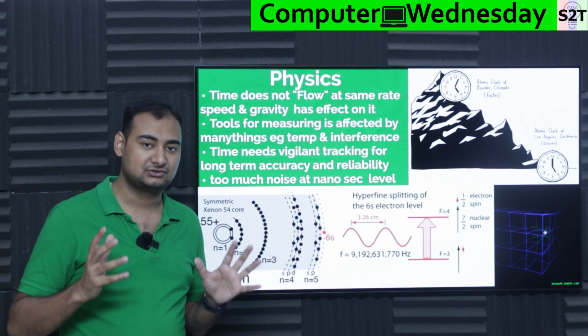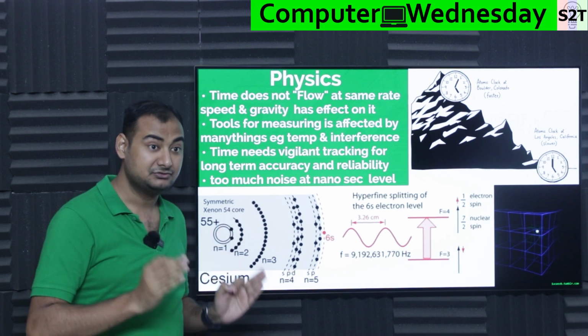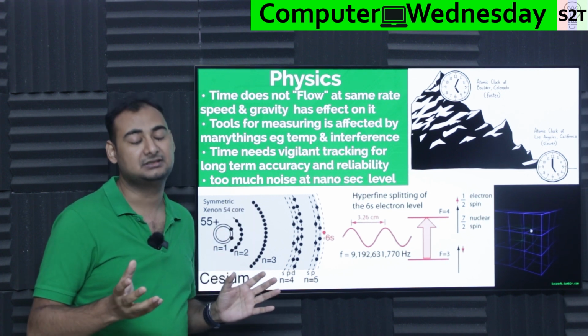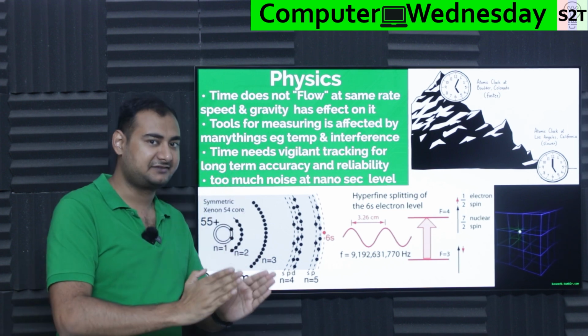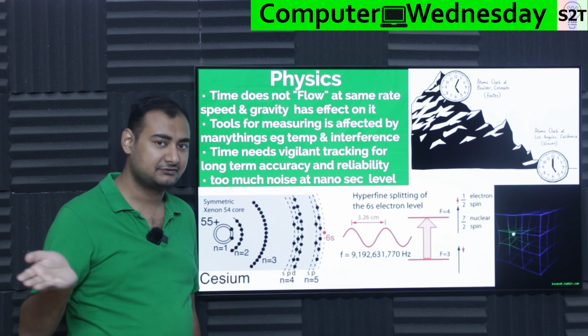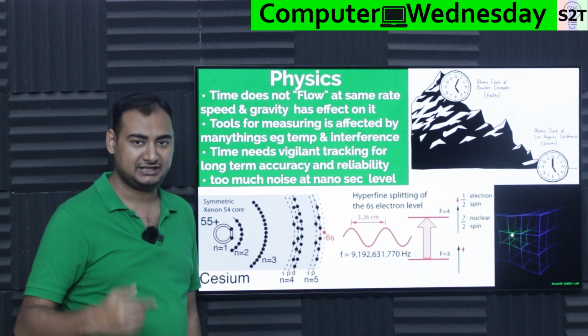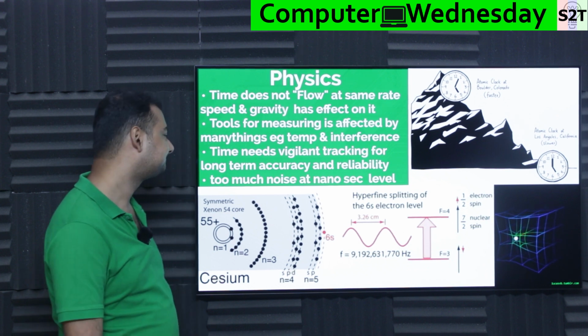And that's why atomic clocks are so high grade. They are not an oscillator that is affected by things. Generally a very pure atom sample is used, and it's like, dude, I'm only going to do this thing at this exact frequency. Exact. In the case of cesium, this is the exact frequency. In the case of rubidium, it's a different frequency, but you get the point. There is a feedback loop that ensures that you are just right.